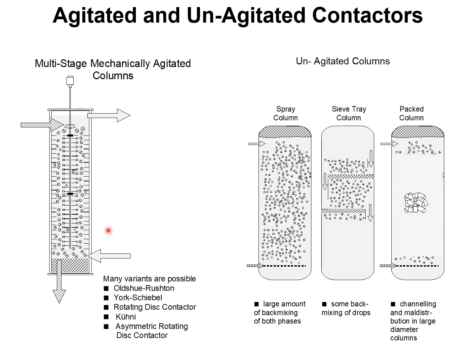Consequently, increasing the rotation speed beyond a certain point may be counterproductive. Indeed, it is a part of common folklore within the petroleum refining industry that an RDC column works best when the agitator is switched off. I leave the discussions at that point and move on to